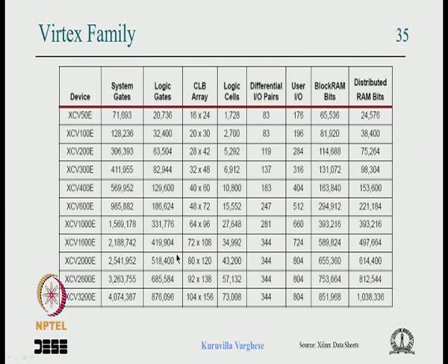A very important specification as far as an FPGA is concerned is the array of logic blocks. How many logic blocks are there? Take this particular device, XCV100E: there is an array of 20 into 30, 600 logic blocks.